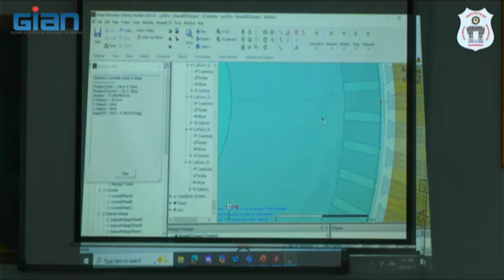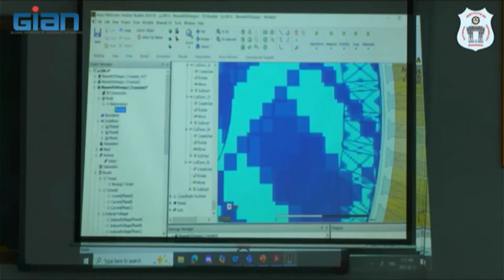And if you want mixed eccentricity, you have to move both a little bit in one direction. Right? So that is how we will do it. And when you do that, because of the software setting, we may have to delete this moving circle first, move everything and redraw a moving block and do the simulation. Otherwise, you will encounter an error in this software.